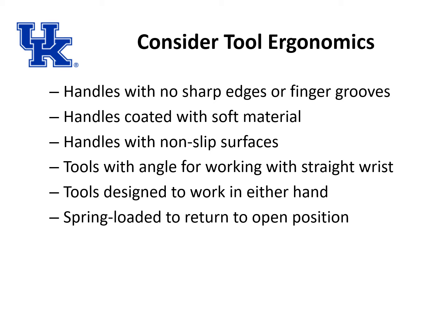Select tools that are designed to work in either hand. You can prevent some repetitive motion by switching hands. Find double-handed tools that are spring-loaded to return to the open position so you do not have to open the tool as well as close them.